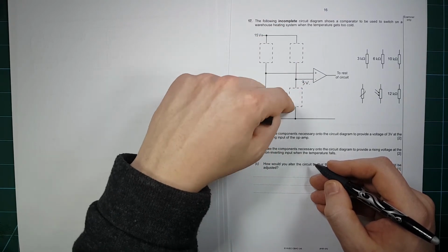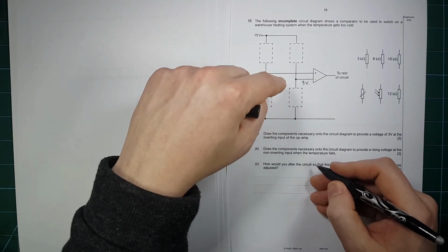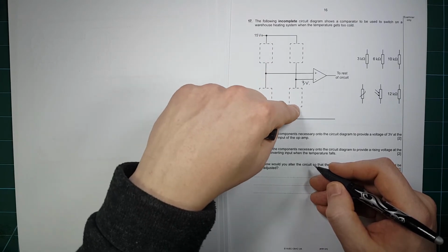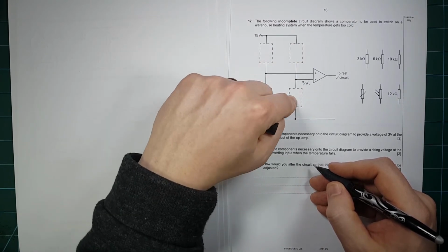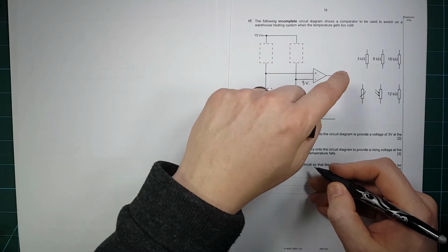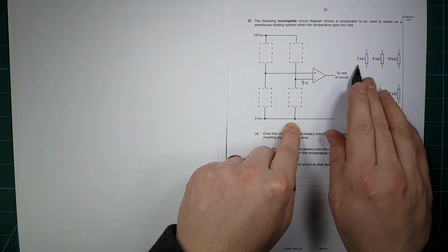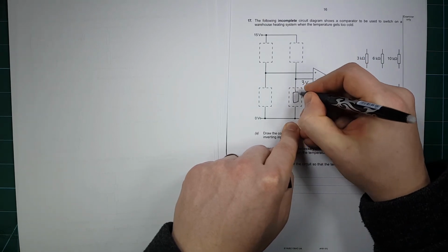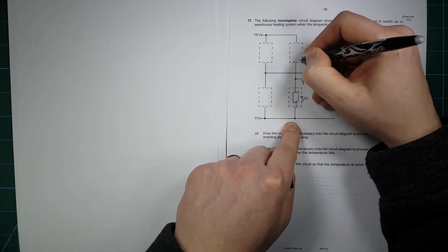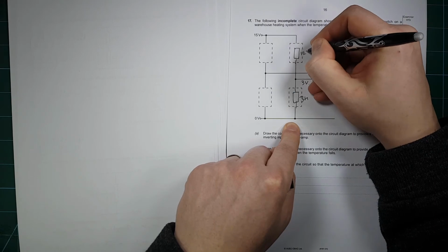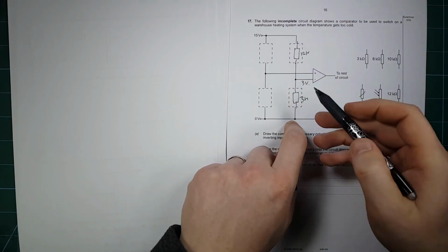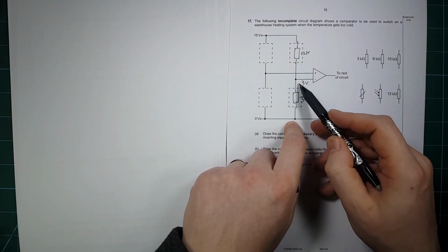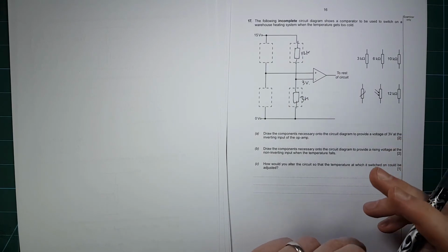And we've got 15 volts, so ideally we'd want numbers which added up to 15 here, 3 here, and 12 here. And lo and behold, we can do that. So there's 3K there and 12K there. So if you use the potential divider equation on that, you figure out that that was 3 volts there.